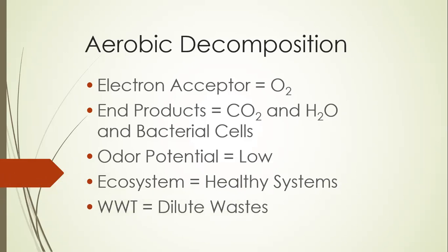Basically, aerobic decomposition is targeting wastewater with low BOD, right? So BOD around 100 to 300 can be the best candidates for aerobic decomposition of wastewater. So aerobic systems can contain activated sludge and variants of activated sludge mainly.